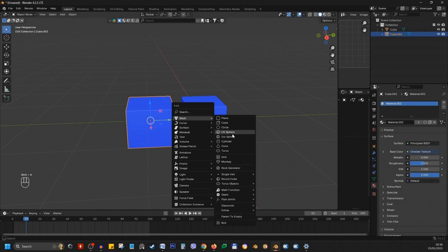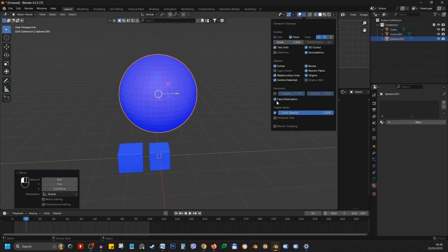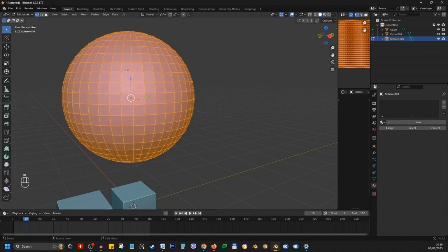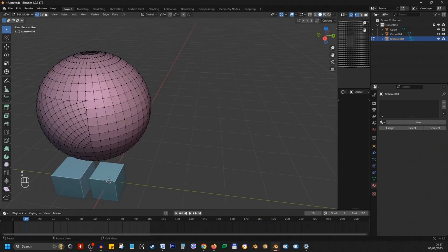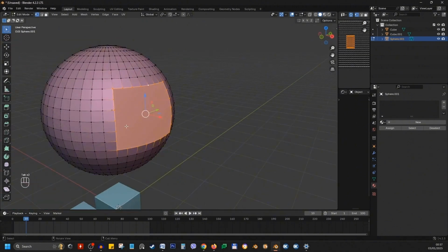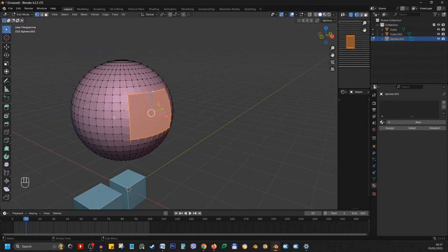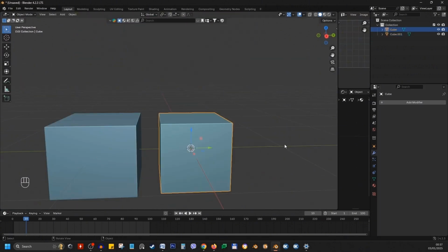But if we play around with a UV sphere, for example, let's turn off face orientation now. Let's say I delete all these vertices here. Now, fixing this is not that easy. I would need a lot of adjusting to get the original shape back. But these here are modifiers. Modeling with modifiers is a non-destructive way of working, meaning that we don't really change the original shape of our mesh. Let me show you.